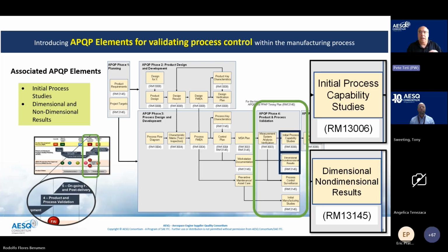So Eric and Rob went through the flow map that led to the PFMEA, that led to the assessment of risk. Risks are mitigated through controls. Now, they don't all have to be SPC related, but when a customer provides key characteristics on the drawing, we call those product key characteristics.